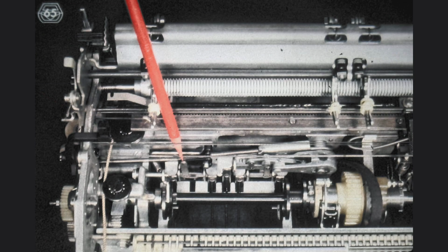Manually try to depress the tilt crank at the point indicated by the red pencil, and notice how the motion is transferred horizontally toward the left in order to rotate the tilt arm. You will notice that the tilt arm has a tilt pulley on top of the arm, and that around the pulley runs the tilt tape. The tilt tape has the ability to move the type element in a vertical plane. So that we can see the whole mechanism in one picture, let us turn to a drawing.